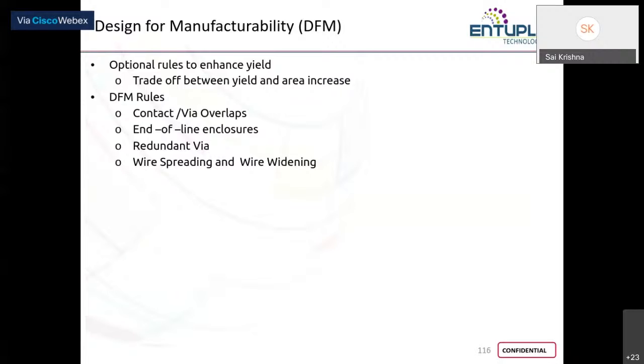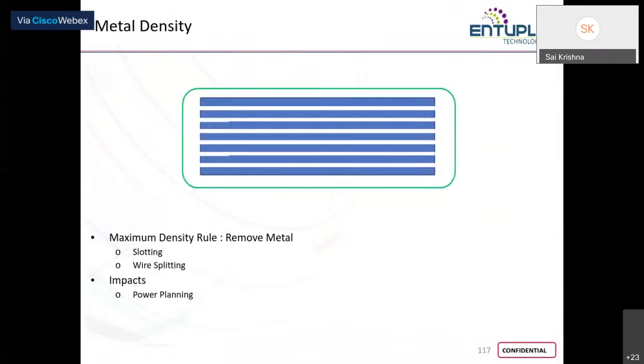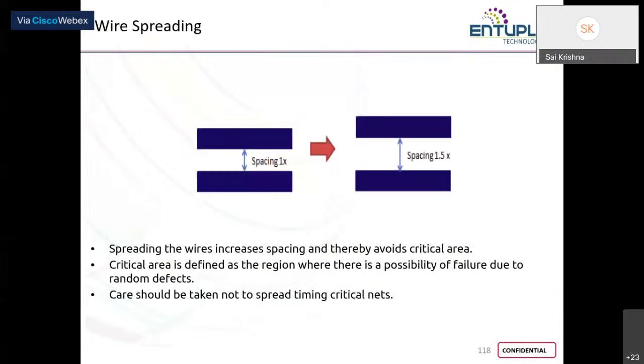There'll surely be wastage, but how many chips you are able to take out is what you consider to be your yield. In case your die area is not giving you proper yield, you may increase it, you cannot decrease it anyway. So you will increase your area using filler cells, follow certain rules, make sure everything is in line, and get your chip fabricated.